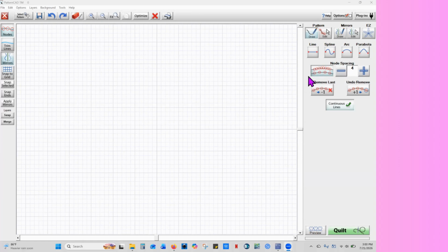I want to draw your attention to this area right here, what we call with your nodes on. And how you turn them off, let me just show you. You click on that button and then you'll not have any numbers in there, and that would be considered nodes off. So let's turn them back on for the moment, and let's not worry about the number that's in there for right now, but let's just draw a simple line. So we're just going to draw. You left click and then you draw. When you unclick the button, you'll notice that it doesn't draw anymore.